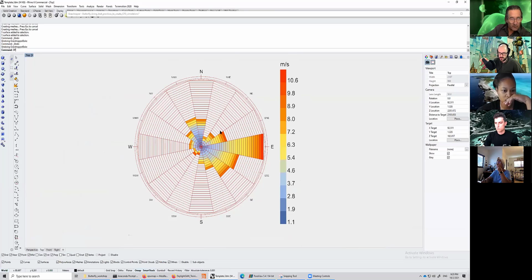So this sort of nexus here, from a bit before east and a bit before south, is where you want to focus when you're designing for natural ventilation, and also north and northwest. So you see that there is a sort of two-direction importance, right? If you were designing a building and you wanted natural ventilation, and in that case you really want to capture cross ventilation, you really want the wind to cross through your building, right? You would imagine some orientation between those two, something that captures at least one of the two. So this is a very rule of thumb without even simulation: how should I orient my buildings?